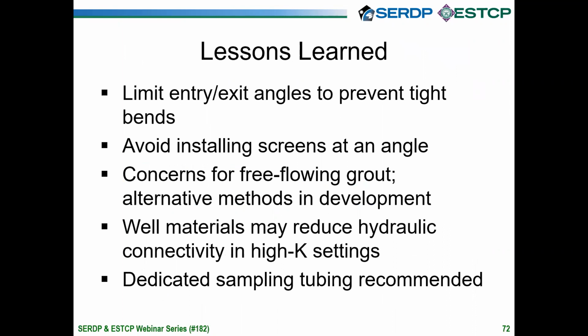There are a number of lessons learned that I'd like to note. First, the entry and exit angles of the wells should be limited to prevent tight bends, which aid in access to and sample collection. The screens, as I mentioned several times, should be installed horizontally, not at angles. Also, we've noted the geotextile screen wrap may reduce hydraulic connectivity, particularly in high K settings, and may be less of an issue in low K settings. Finally, we'd like to recommend dedicated sampling tubing for each of the well screens.